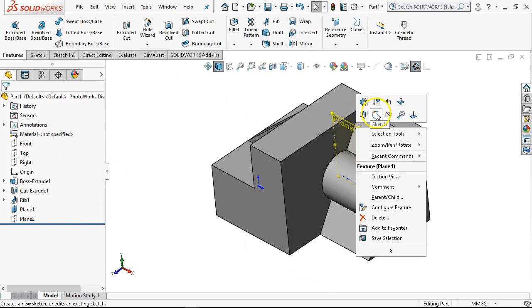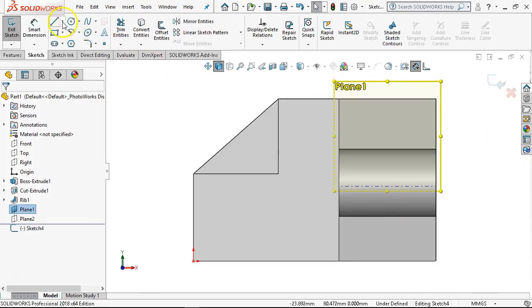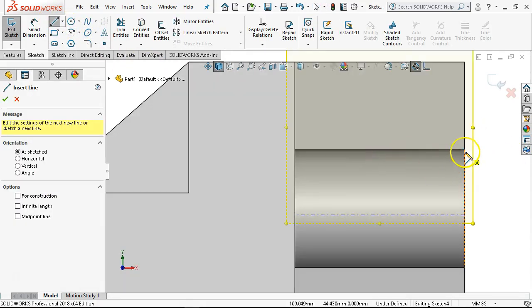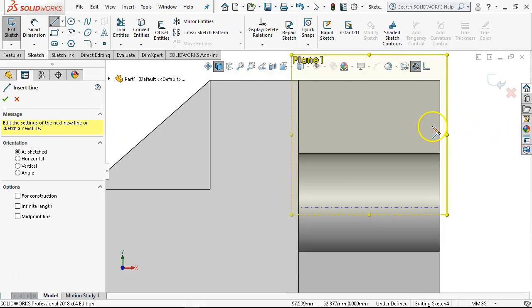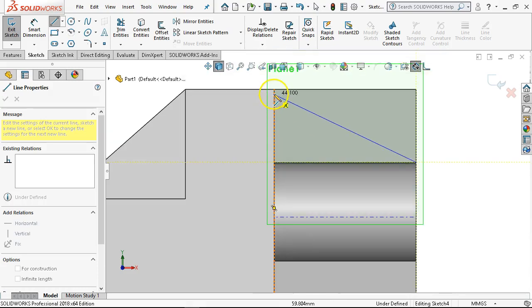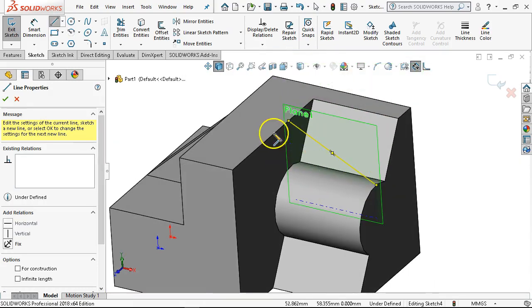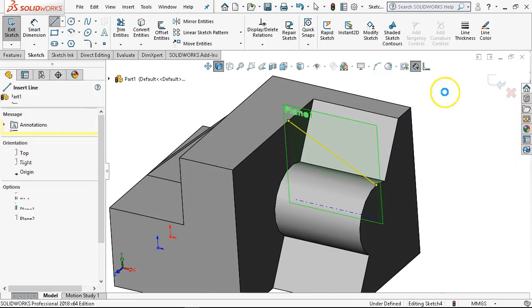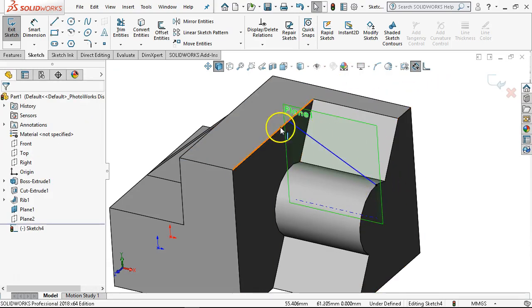All right, so back to setting up the rib. We'll open up the sketch. And watch out for, on the cylinder, that if you go directly to that point, you're having curvature fall away from the rib, and it's either going to generate 0 thickness or it's not going to be able to calculate. So I'm going to go to the endpoint first to illustrate. Prismatic shape, this rectangular shape, not a problem. It's not even going to think about it.